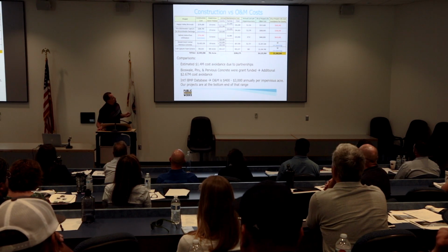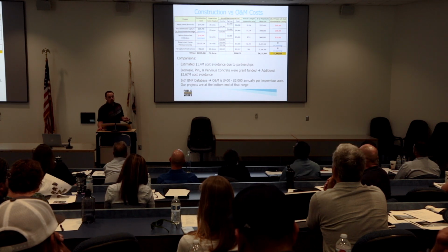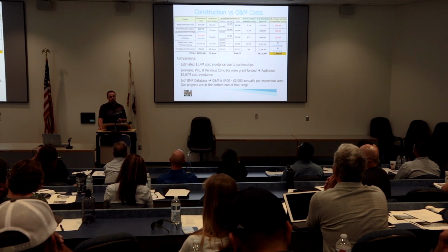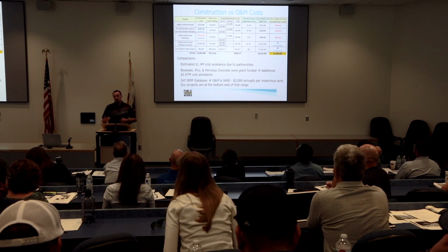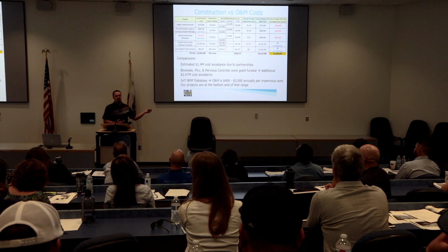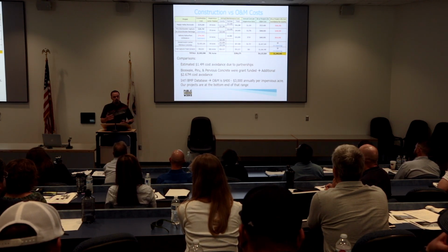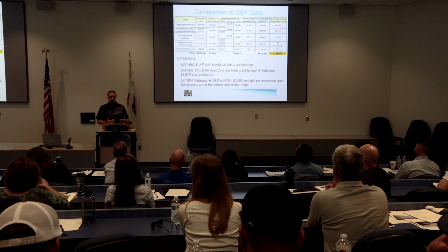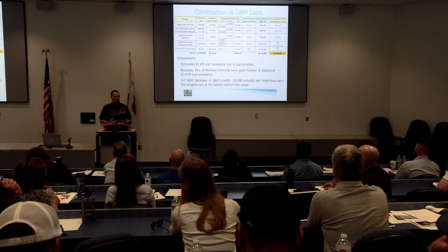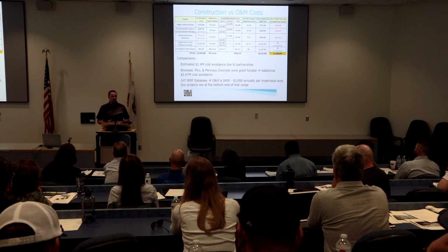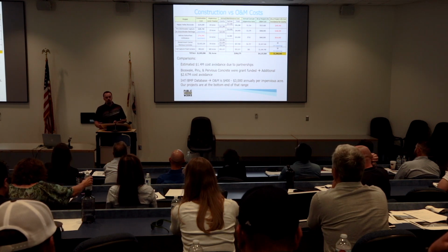I didn't break it down by impervious acre here, but I did for the O&M. So here you can see all of these areas generally fall within this range, and usually the lower end of the range. So when you're designing projects, you should be thinking about the O&M and what this is going to cost. For instance, if say the city of Thousand Oaks bought a Vector truck to do this stuff in-house, a lot of the pretreatment stuff you're putting in a future project should also require a Vector truck, so you're using the same equipment. You're not having to hire someone else to come out and do confined space or things like that if you don't have to. So it's trying to think ahead and keep similar equipment helps a lot with long-term costs.